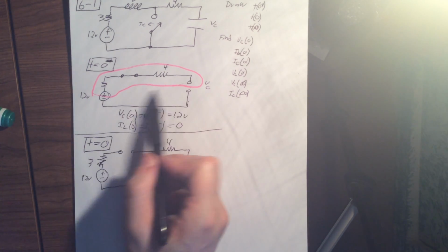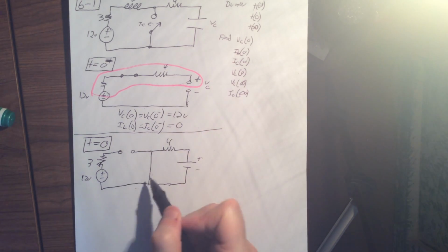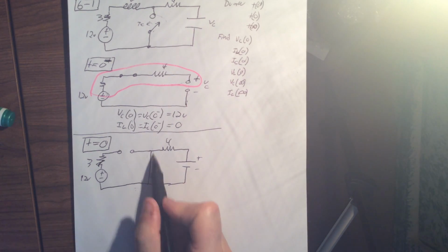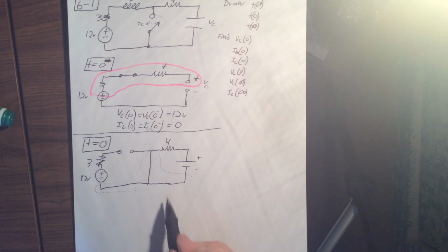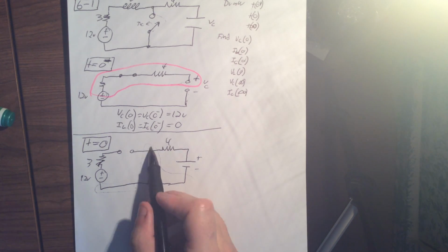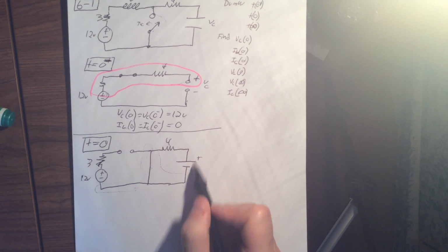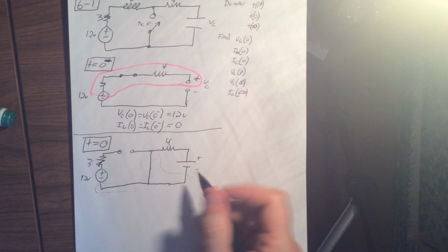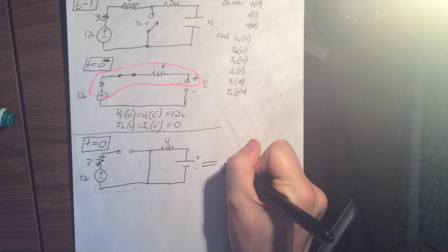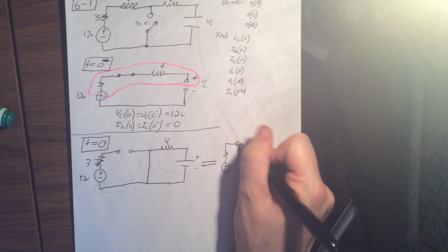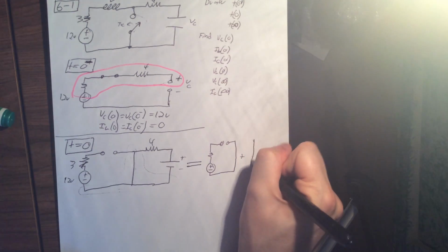After all this period of time up here, this capacitor is charged up over here. Now, when we flip this switch right here to 0, this is going to short circuit this circuit. So this whole bit all the way up here is ground, because look, it's just one giant supernode the whole way across. It's ground no matter where you go between those points. So that means that this is actually two different circuits. It's this circuit, which I'm going to draw really simply, plus this.